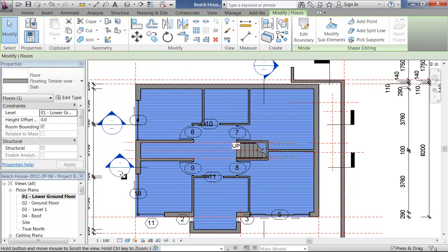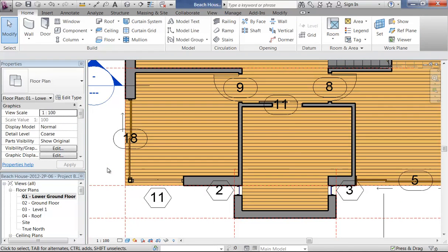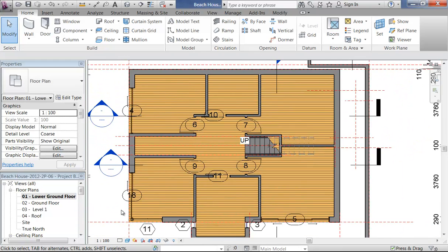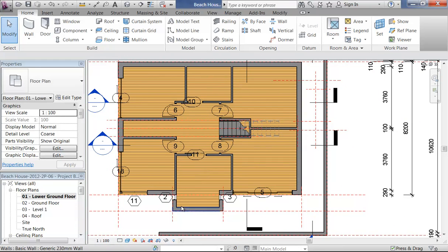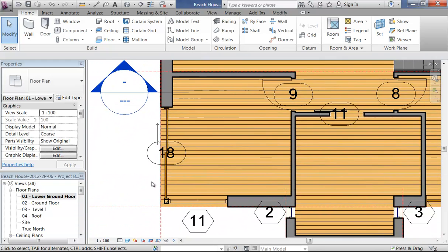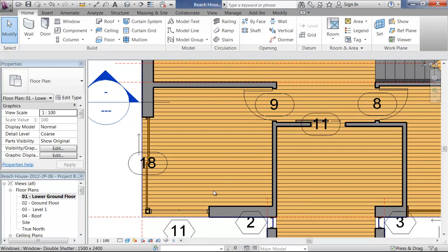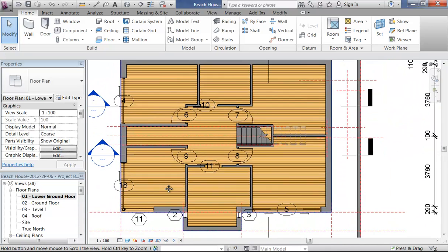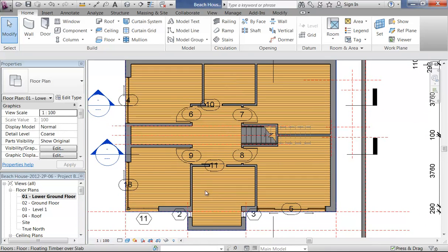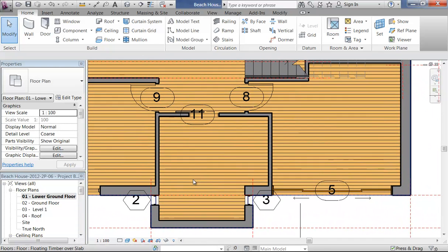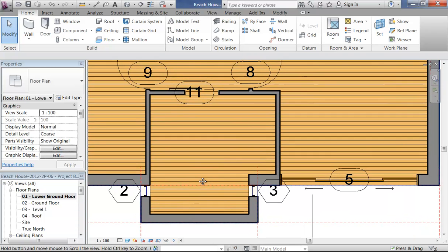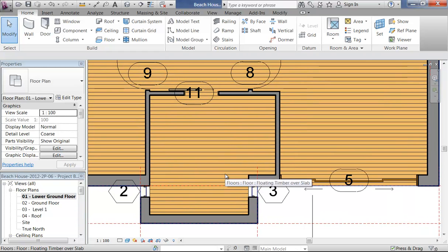And now in this shaded view I can see that timber material covering that whole floor. Now there are a few issues that you can see now with the doors and window thresholds, because it probably shouldn't show like that in plan, and I'll fix that afterwards. You'll see how to fix that once I've done the bathroom floor though, because I'm going to fix it the same way. So I want this bathroom area to have a tile material instead of the timber flooring.